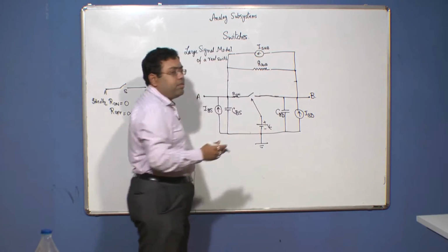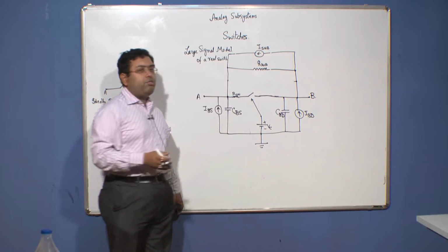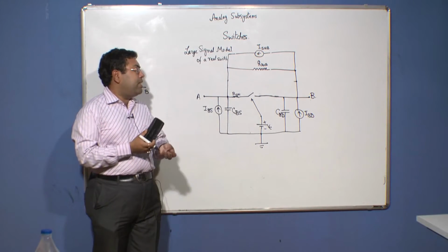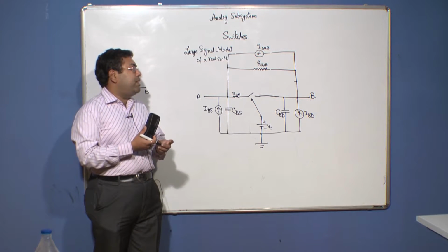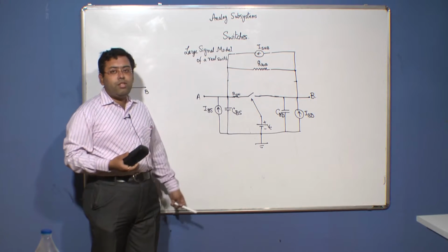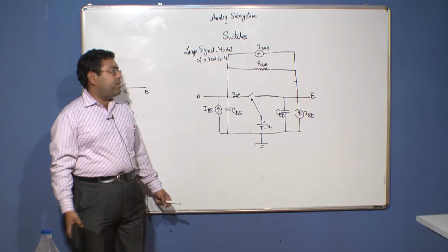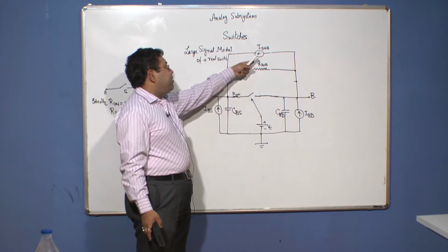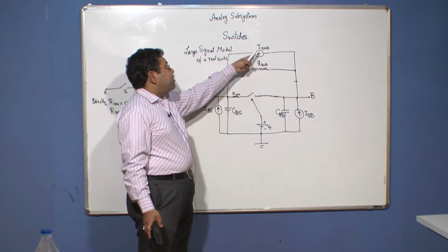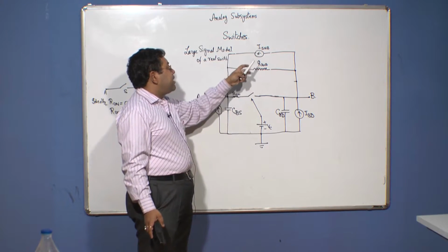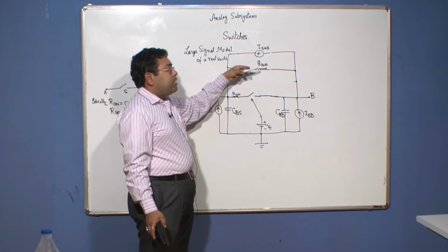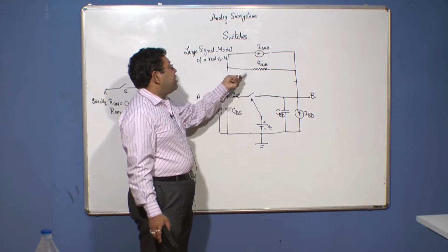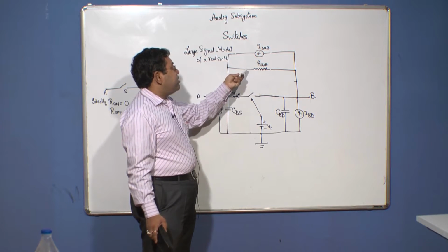Below the threshold voltage we normally assume that the drain current of the MOS transistor will be equal to 0, but in reality there is a feeble current that flows between the terminals of the MOS transistor even when the transistor is operating in the cutoff region, and therefore this phenomenon is modeled by the subthreshold leakage current given by I sub over here, and the potential drop that occurs because of the flow of the subthreshold leakage current is modeled by this subthreshold resistance R sub.